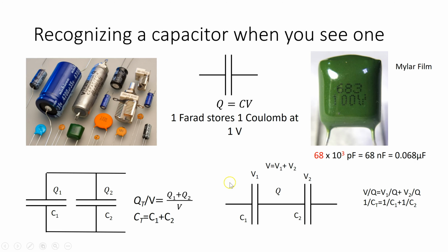I've gone on here to show you a derivation of the formulae for capacitors in series and parallel. I don't think you'll ever use this to make practical capacitors for an electronic circuit. You'll just buy the right values. But it's good to know these formulae because in electronic circuits, stray capacitance, often in parallel with, for example, the input of your operational amplifier, will affect its performance.